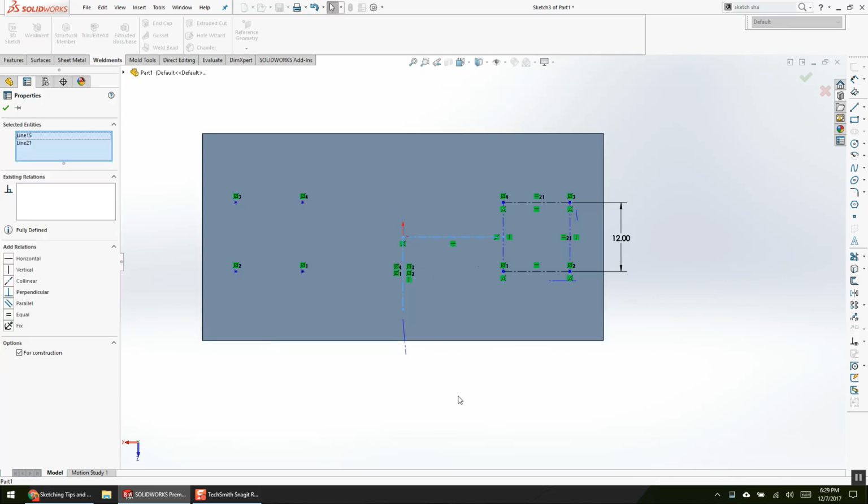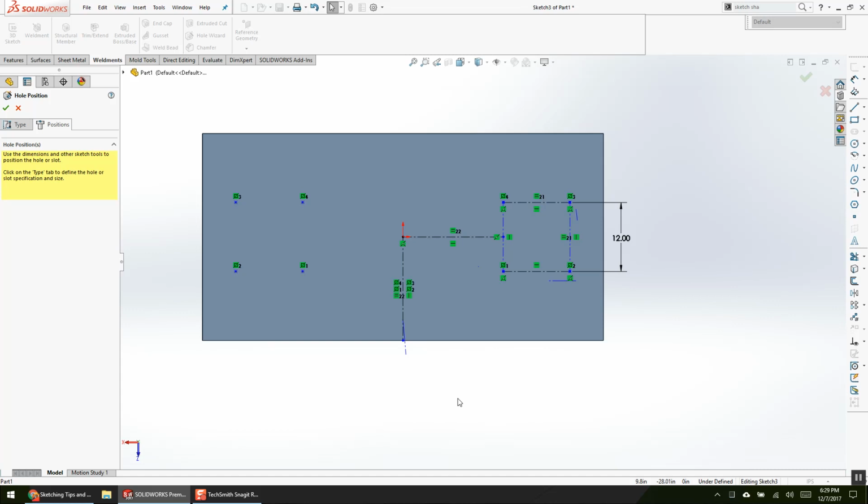The one thing I don't like about that is when everything changes, what's the first thing you do when you change a sketch that has a mirror in it? You totally delete whatever you just mirrored. And then you fix your sketch and you remirror it. So part of my liability of all future changes is more than likely I'm going to delete whatever I mirrored. Dimension from that and pick the center line and go to the other side of the drawing.